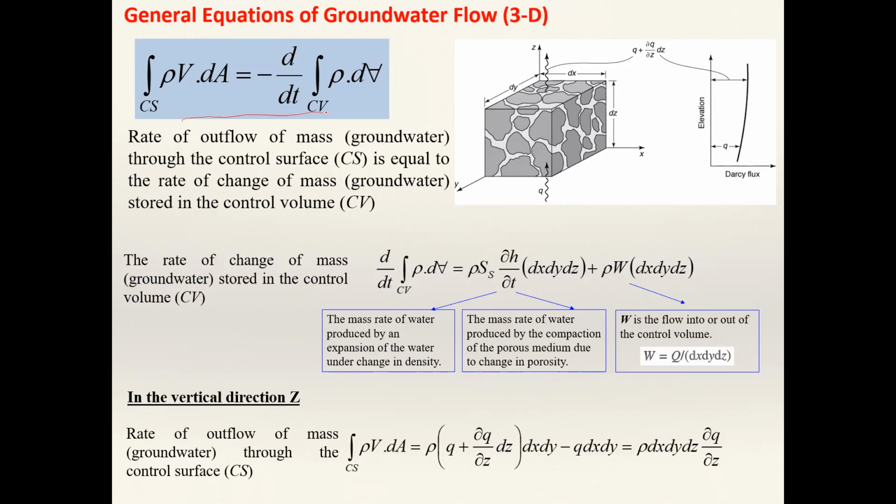In the Reynolds transport theorem, you have two parameters called the extensive property and the intensive property. If you consider the mass as the extensive property and B is equal to 1, in that case, you develop the continuity equation, right?